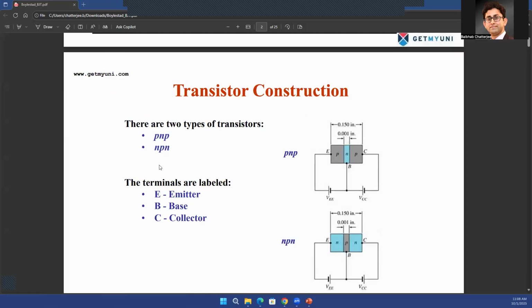So transistors, in general, some books call them 3-terminal, and some books call them 4-terminal devices as well. We'll get to see why some books do call them 4-terminal devices, and in reality they are 4-terminal devices. We just don't use the 4th terminal, which is the bulk or the body of the semiconductor material, because any transistor is created inside a semiconductor. And you have P, N, and P, creating basically the BJT transistor within a semiconductor.